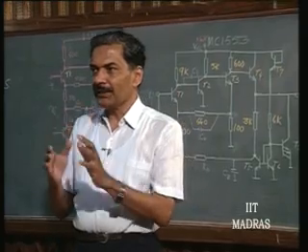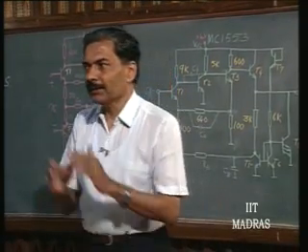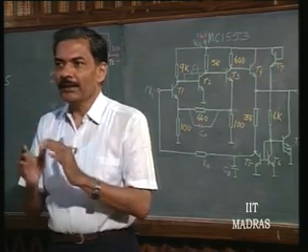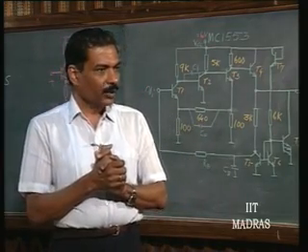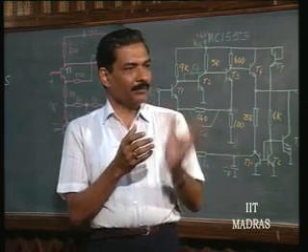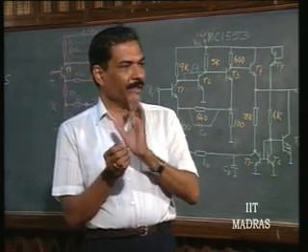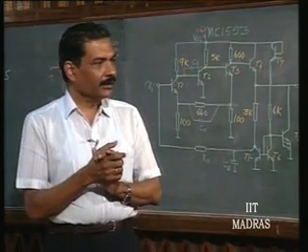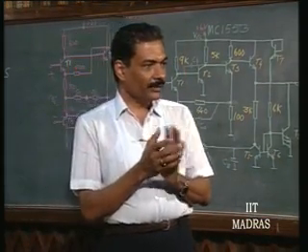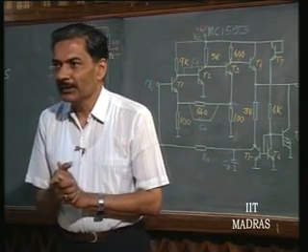This is a characteristic feature of all high speed amplifiers, comparators, Schmitt triggers, anything that you think of in terms of integrated circuits, where we design high speed comparators, wideband amplifiers or logic circuits, we must use low valued resistors and be happy with low value of gain.